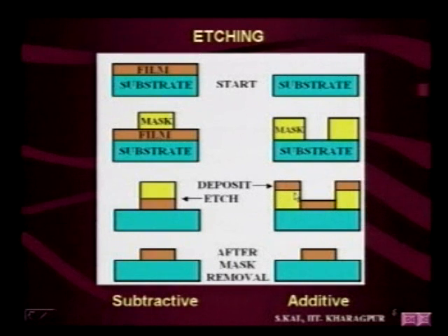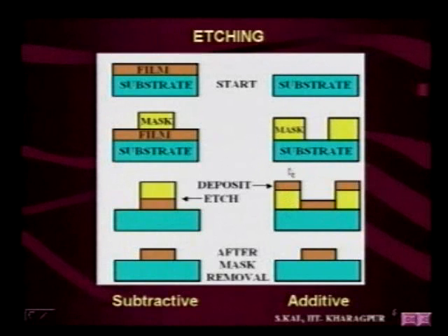That means the film on the resist and the film on the substrate should not cover the side wall of the resist. If it is thick enough, so there is no window here and there, the resist film will not be attacked by the removal solution and you will not get the pattern transfer. This is a very important point when you do the lift off technique. This particular technique is known as the lift off technique. Additive process, another name is lift off, because you are lifting the photoresist off along with the metal film or the film which you want to pattern.